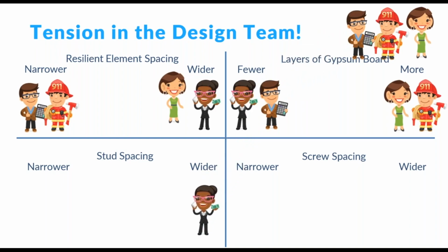All right, so stud spacing. Again, developer wants wider studs, less labor. In talking to a lot of estimators for drywall and steel framing companies, they'll say they'll always try to push to using 24-inch on center stud spacing, maybe not always, but often when it makes sense, they'll push to wider stud spacing but a thicker stud, because the increase in material cost for the thicker stud is more than offset by the decrease in labor, because labor just tends to be much more expensive these days.